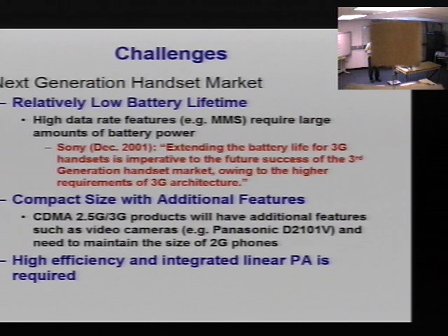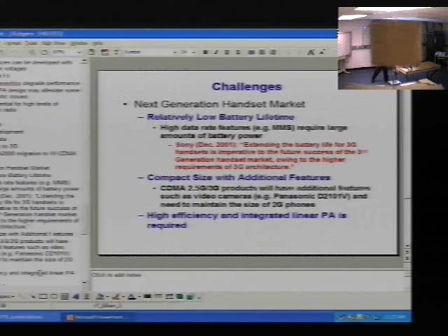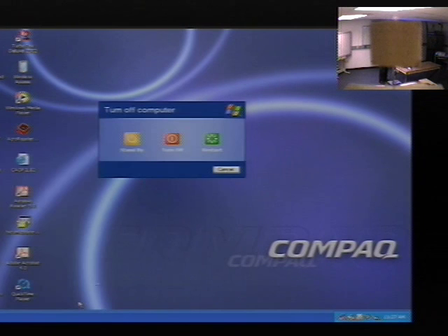So in the kind of modeling that you are doing for 3G, do you have a standard reference model for the channel including amplifier nonlinearity? For the amplifier, from the analog portion, we usually just get the time jitter stuff. So the phase loop accuracy is being modeled, but trying to get the power amplifier shape into the simulation, not yet.